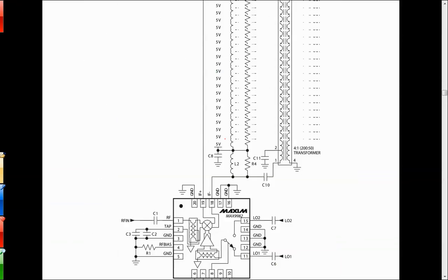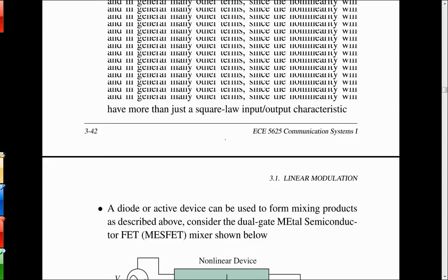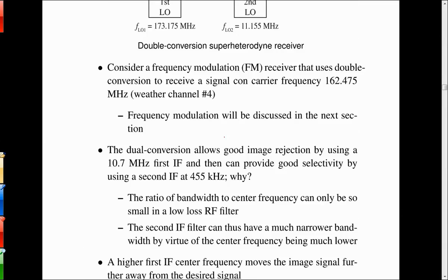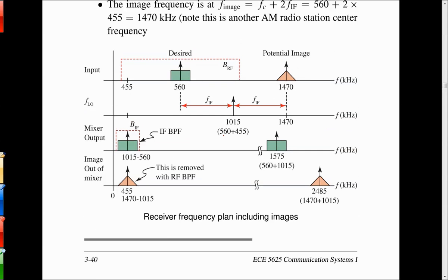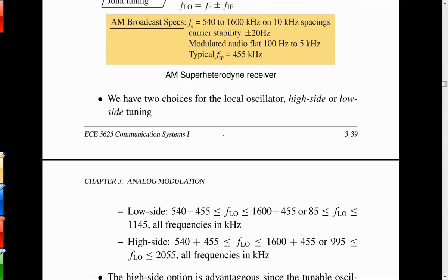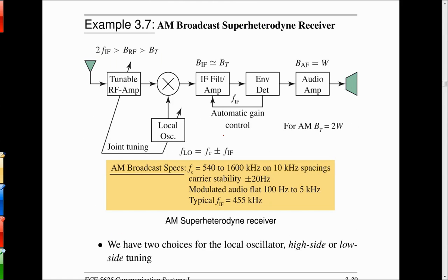So let's go back and look at the mixing stuff. To me, the best example is this spectral layout, and the math is in between the block diagram and the pictures. So frequency translating and mixing, if this is a radio receiver, it's just saying that you want to move something to a common location that's useful for all the purposes of demodulating and recovering that signal.